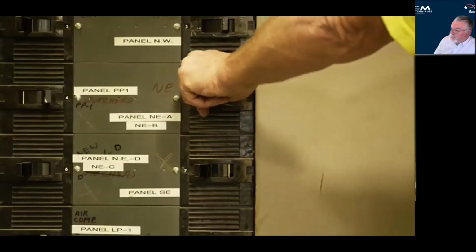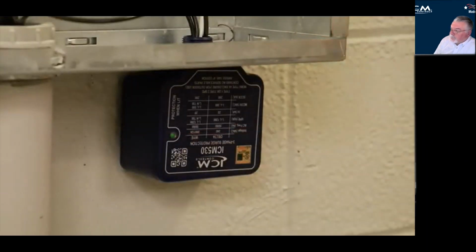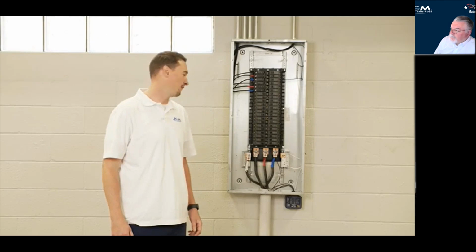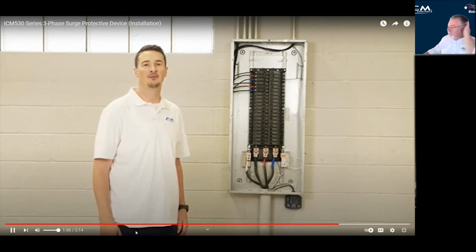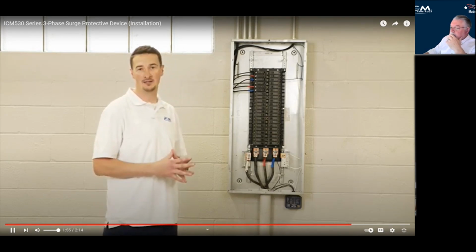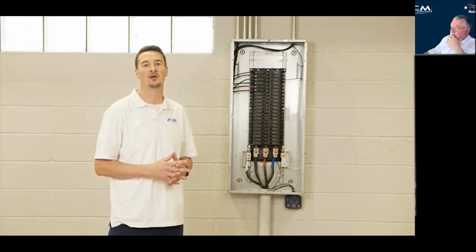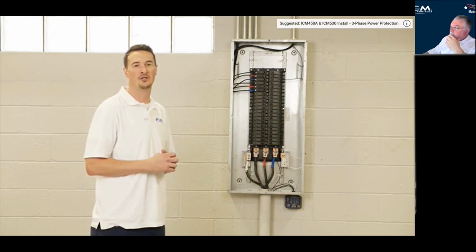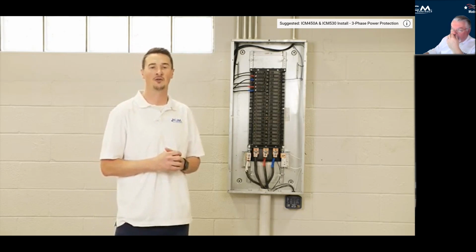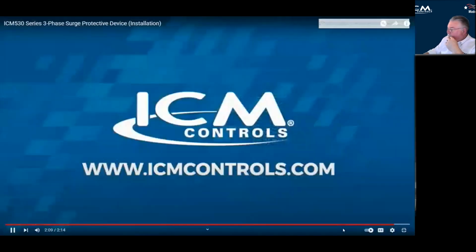Turn on the power to verify the installation was successful and the LED indicator is illuminated green. That concludes this fairly easy installation here of the ICM530 surge protective device. Just remember that if the LED light is illuminated, then you are fully protected, and if it is off, then the device will need replacing. If you have any questions or concerns, you can reach out to ICM Controls technical support or visit the website at icmcontrols.com.